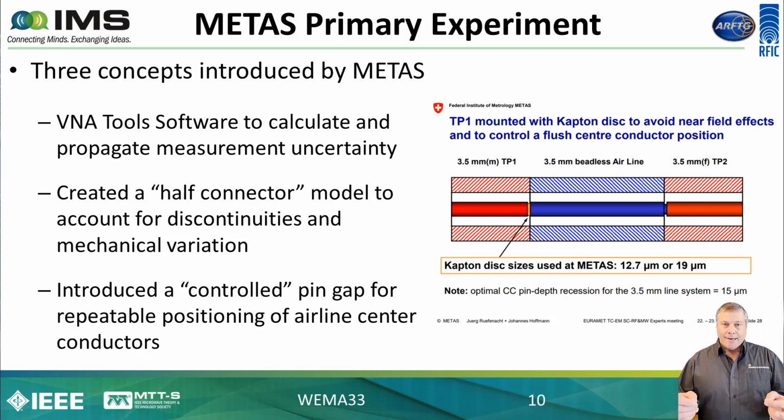Now, by design, that capturing of the center conductor cannot be a compression fit. If we have the male and female connectors pushing or putting pressure on that center conductor in a compression fit, it will cause the center conductor to bow or deform in shape. And we cannot allow that to happen.